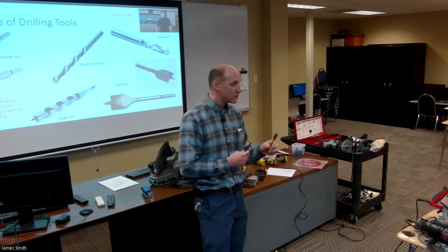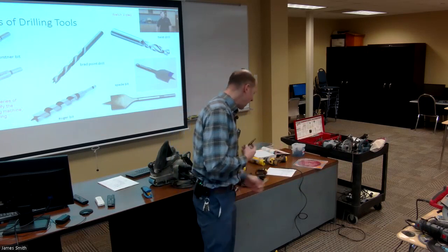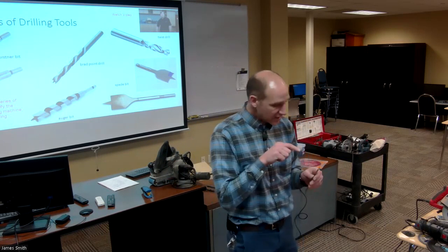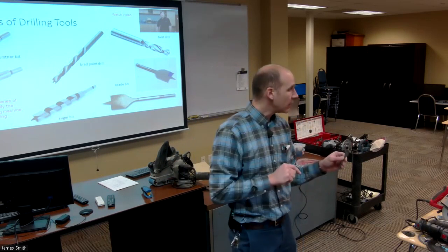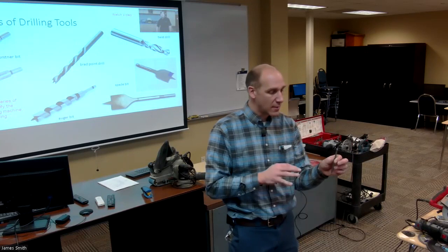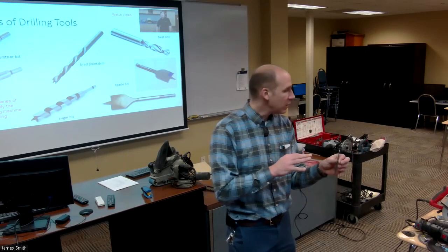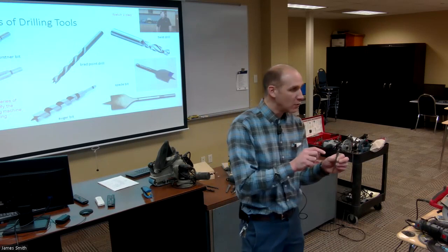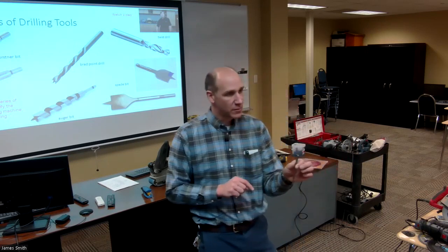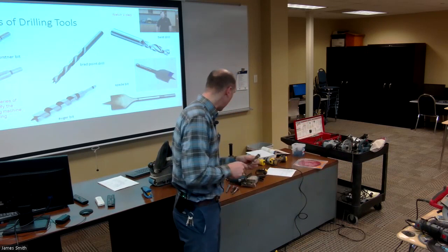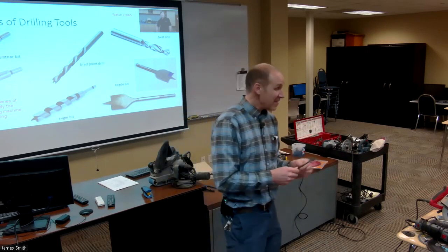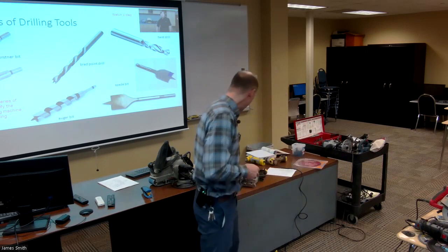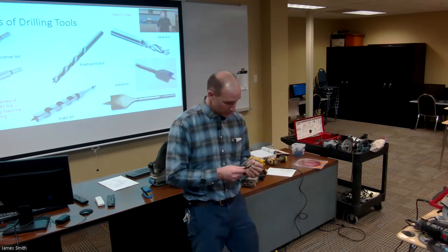Just don't hit any nails. And that's the other thing too: if you do hit a nail, you can just take a file and resharpen that. There's not any complex geometry, and you don't have to have a diamond grinding tool in order to resharpen one of these bits. They're very easy to resharpen or modify to fit whatever type of hole you want to make. I've done that before as well.